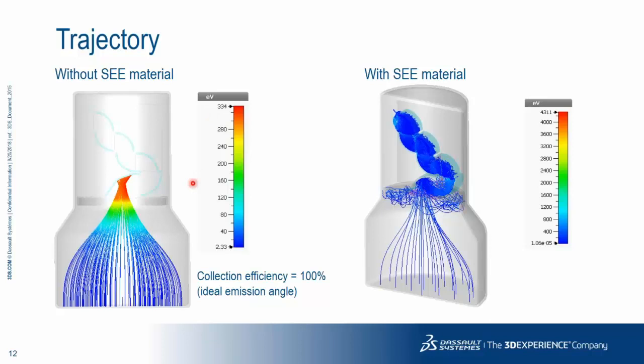And obviously an interesting factor for photomultipliers is how many electrons you can guide to the first dynode here in the middle, because the idea is not to lose too many particles already somewhere here, because your field is maybe not shaped well. You can see in this plot that we have a so-called collection efficiency of 100%. So all particles are finally going to the first dynode, where the amplification process starts. Maybe you can remember, because we see something different later on, that we have a normal emission towards the surface. What you can also see is that all particles land approximately in the middle of this dynode, which then gives a good emission angle for future movement of the particles.